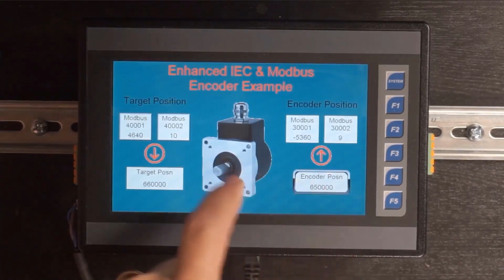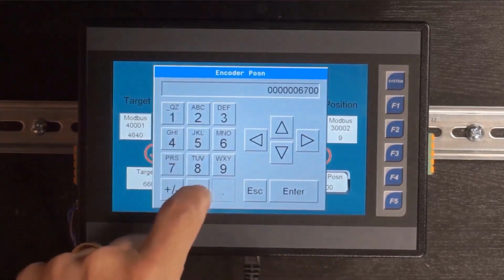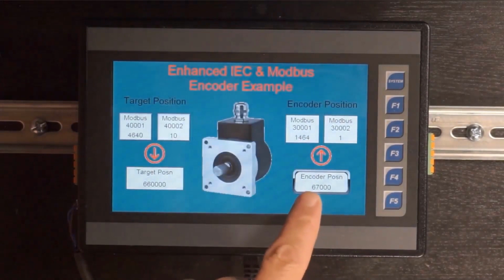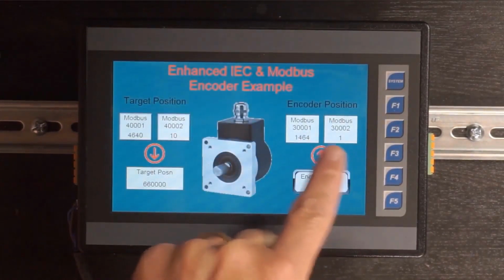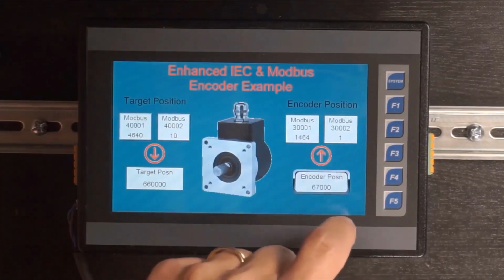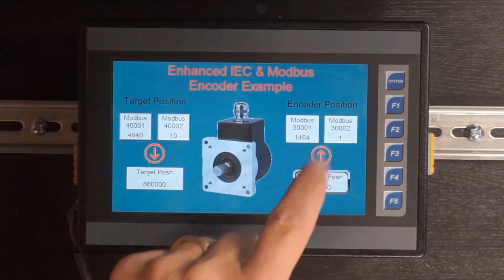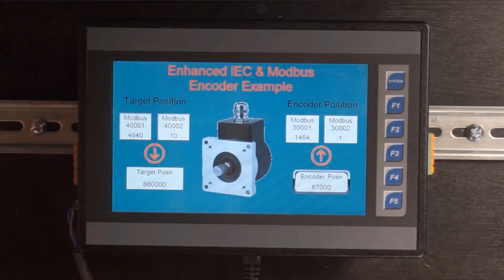And we made this just editable from the screen for demonstration purposes. And then our UDFB splits those into 2 different components at addresses 30,001 and 30,002, where they can be read by the SCADA package and then reassembled on the other side. So, to simulate our SCADA package, we're using Modbus Pull.